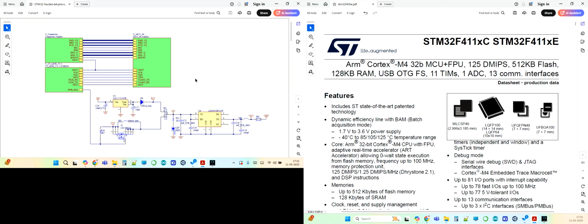And in case you want a 1.8 volt requirement, we might have to use a different regulator, or it's a little complex thing. If we have to see how good this board is designed, whether VDD is distributed at what places, we have to see and then check if this supports 1.8 volt or not. For now, the Nucleo board clearly supports 3v3, which is called the VDD signal, and is connected to the microcontroller.